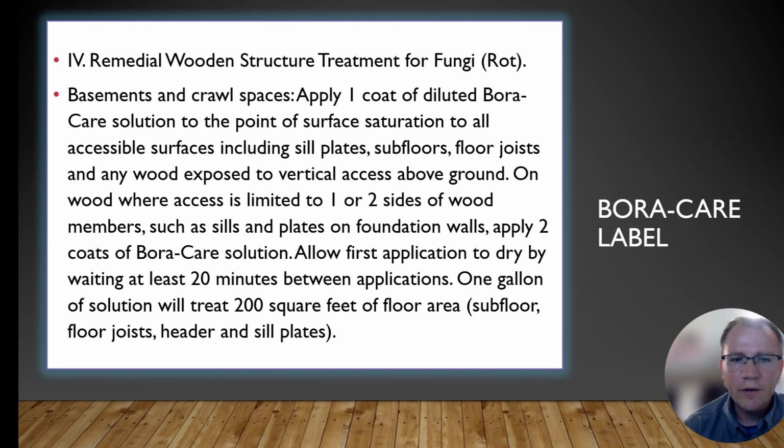On any wood where access is limited to 1 or 2 sides of the wood members, such as sills and plates on the foundation walls, you're going to apply 2 coats of BoraCare solution. So you're going to need to allow the first application to dry by waiting at least 20 minutes between applications. 1 gallon of solution will treat about 200 square feet of floor area, which is going to be like the subfloor, floor joist, header, and sill plates. So there's a lot of information in this section on the label.